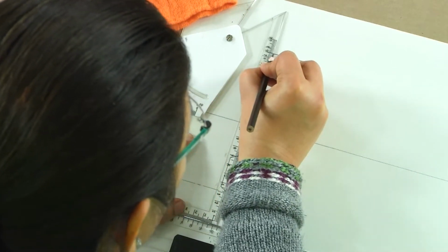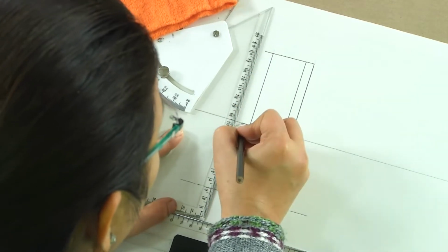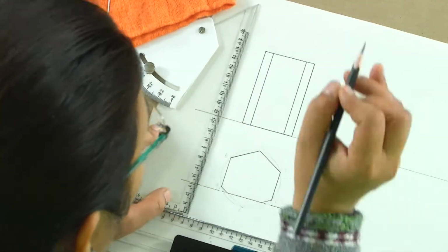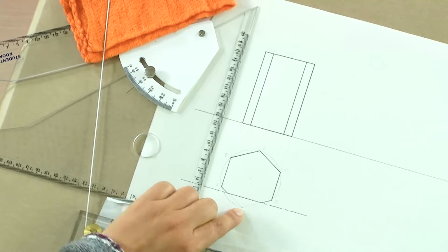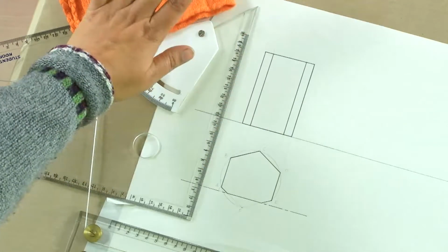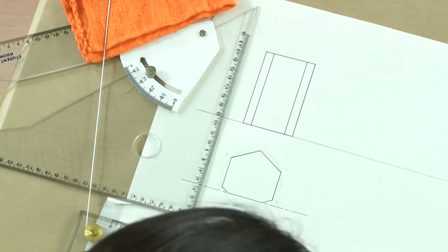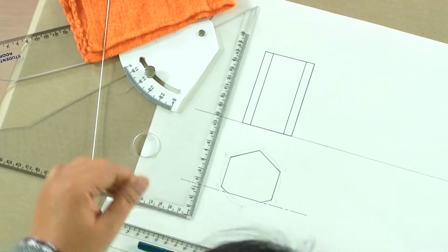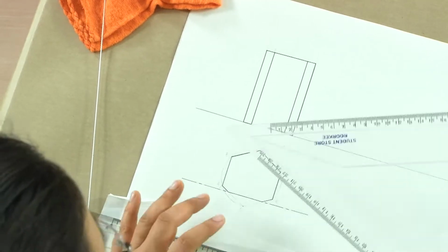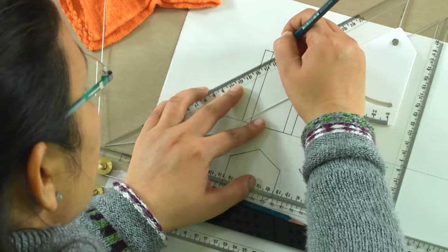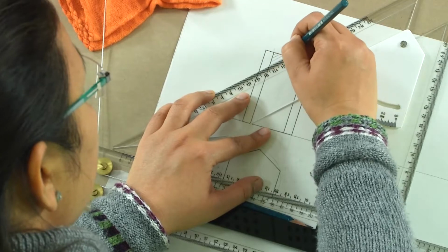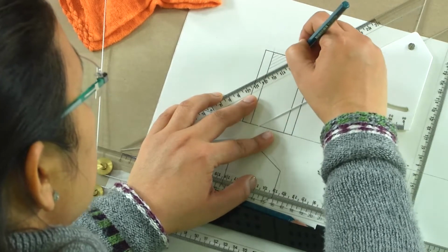Now, the middle edge which we were originally seeing initially when the prism was assumed to be kept, this edge which is F, starting from F, that edge has totally gone. So, we do not see any edge like that there anymore, and what we have to do is to mark that this is a cut edge, because this is what we are seeing. We will hatch it. What does hatching mean? We have to fill this entire surface to represent that